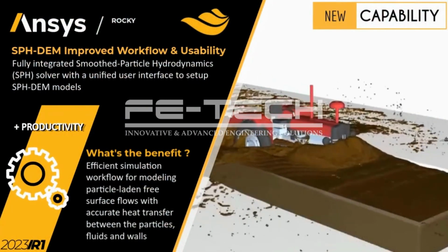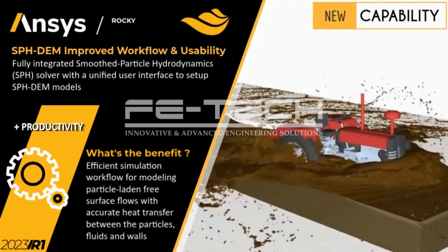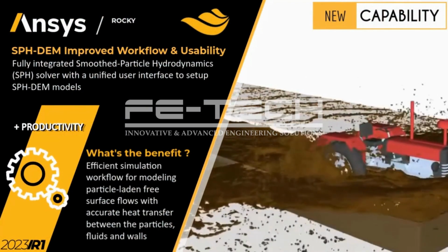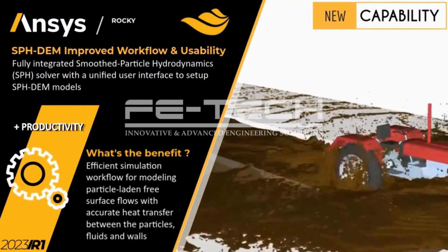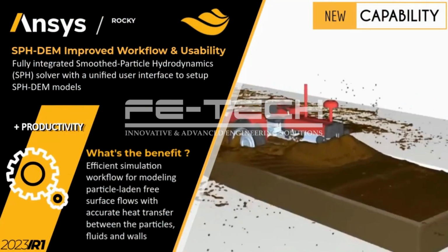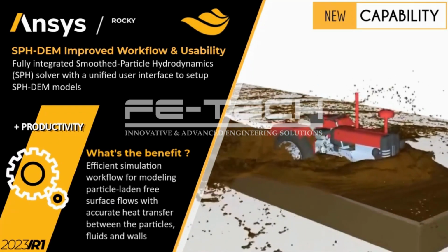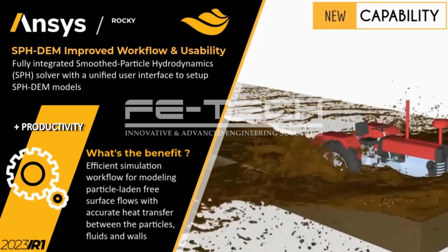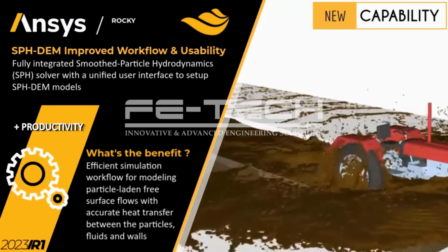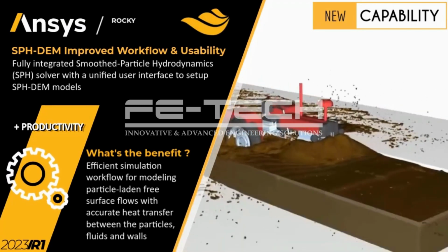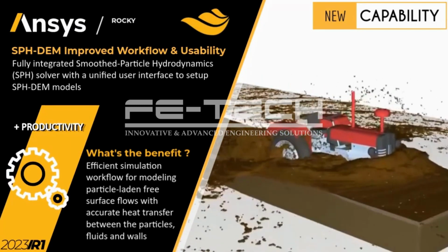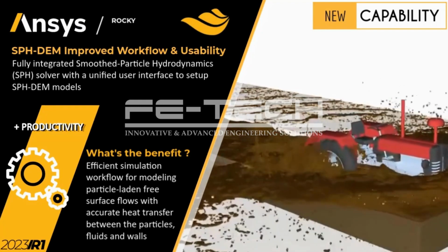In this new release of ANSYS Rocky, we have a fully integrated smoothed particle hydrodynamics solver with a unified user interface to set up SPH and DEM models in the same environment. The new release provides an efficient simulation workflow for modeling particle-laden free surface flows and adds heat transfer between particles, fluids, and walls.